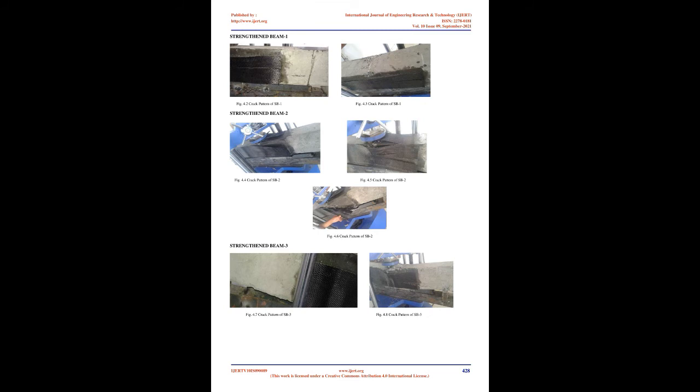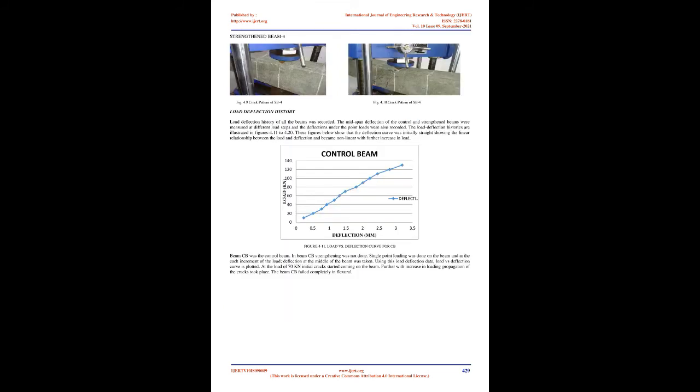Curing of concrete. Curing is done to prevent the loss of water, which is essential for the process of hydration and hence for hardening. Usually, curing starts as soon as the concrete is sufficiently hard. Here, curing is done by spraying water on the jute bags or by spreading wet Hessian cloth over the surface for a period of 28 days.